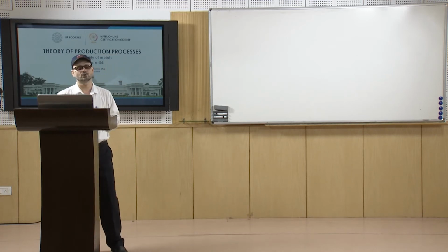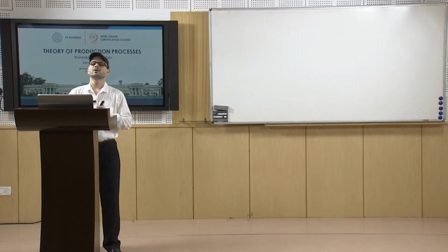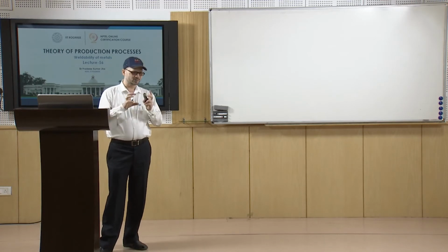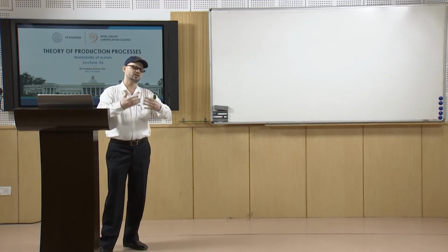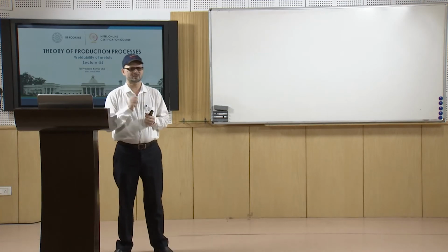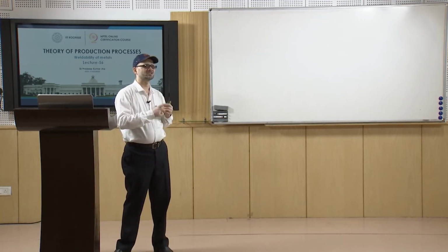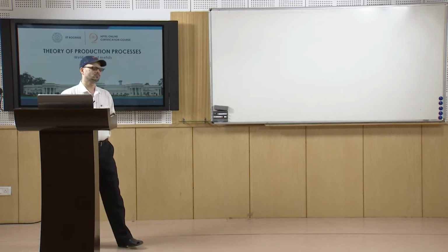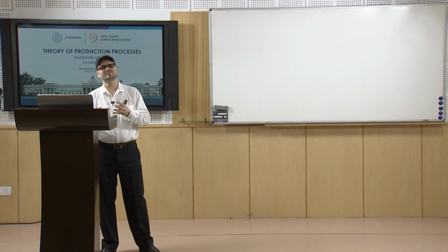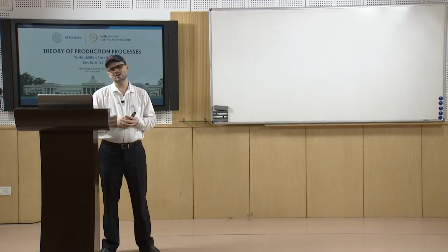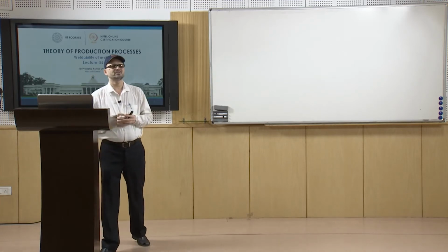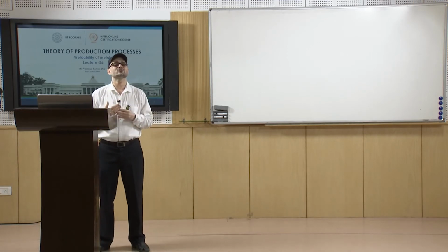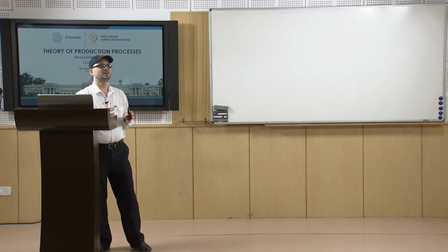What happens is that in the weld metal zone, if you are using filler metal or electrodes, they do not have basically the same composition as that of the parent metal. So, you have some degree of dilution. Also, we put different alloying elements into the weld metal zone, and that basically gives you the dilution. Now, up to what degree of dilution can be absorbed?